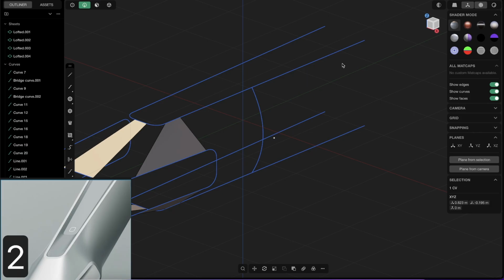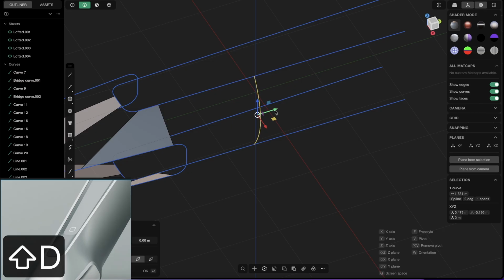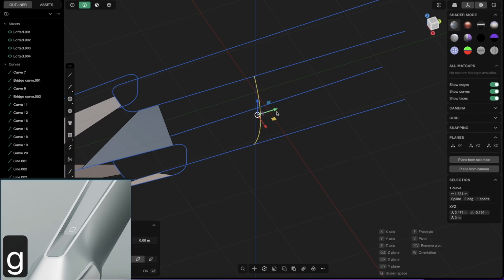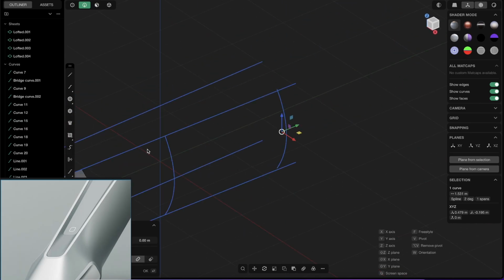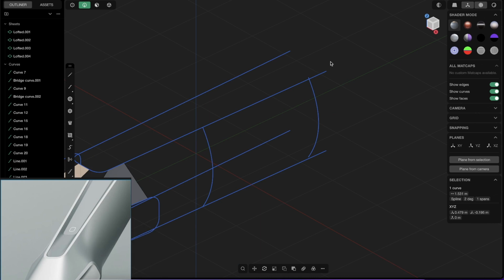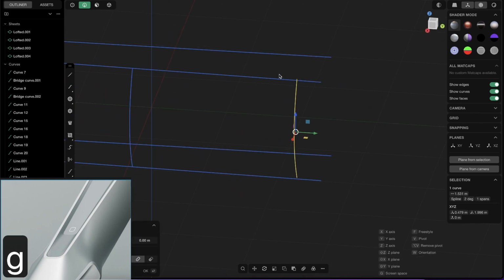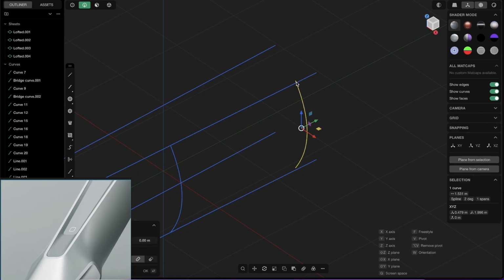And now let's bring the same curve here to the end. So select the curve, Shift D to duplicate. And here with this gizmo selected, if you don't see it, press G. And this gizmo you see, just bring it just back. Doesn't matter where, because right click. So if you select this again and press G again for move, you want to bring this pivot to this point.